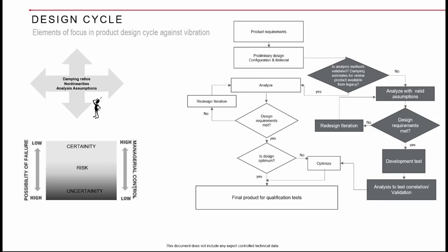Sometimes there will be some stiffness associated with it because of the friction also. So we have to understand how the slip mechanism or the kinematic coupling mechanism is working and how I can model it appropriately. So analyze with valid assumptions. When you don't have valid methods, just analyze with valid assumptions.